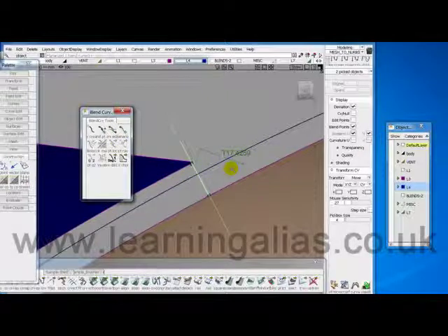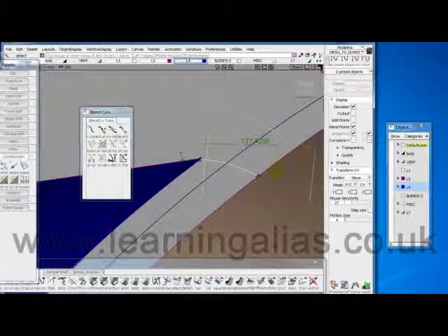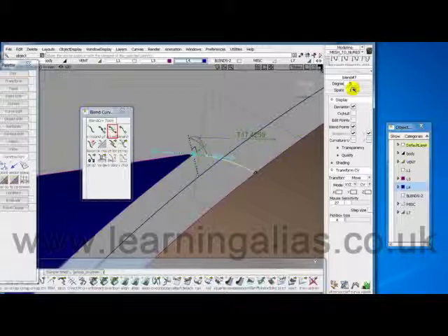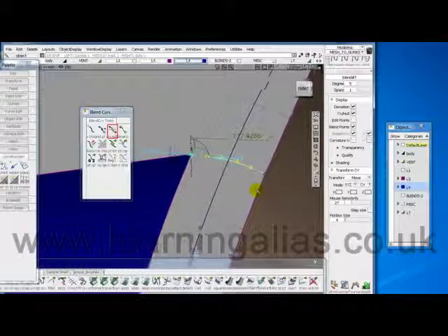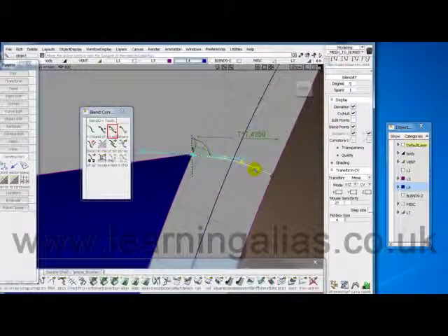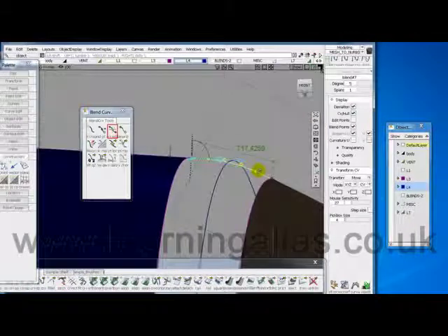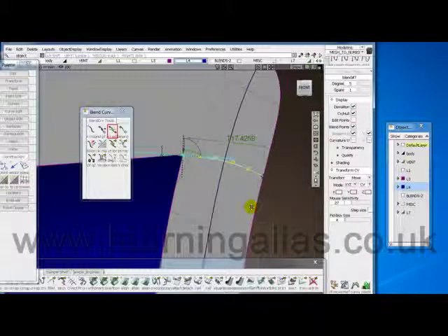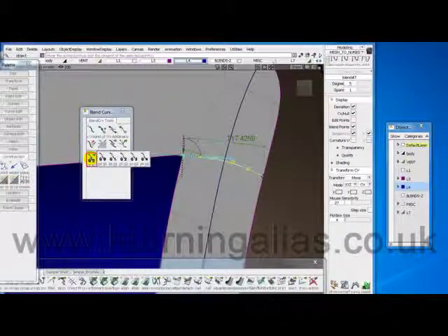That's it, planarized. Now it's always the same with blend curves, same procedure. Put on your hulls, make sure you've got all your points out. This is a degree 5, so 1, 2, 3, 4, 5, that's perfect. It's nicely evenly distributed CV wise, so I'm happy with that. So that's G2, just to be on the safe side, go G0, G1,